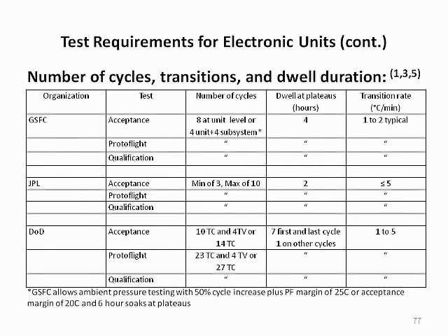In addition to temperature range, government organizations also levy requirements on the minimum number of temperature cycles, the minimum dwell time at each plateau, and the rate of temperature transition. MIL Standard 1540 requires substantially more temperature cycles for units at the protoflight and qualification levels than does NASA. It should also be noted that the actual dwell time at plateaus may have to be longer than shown here in order to conduct the required functional tests.